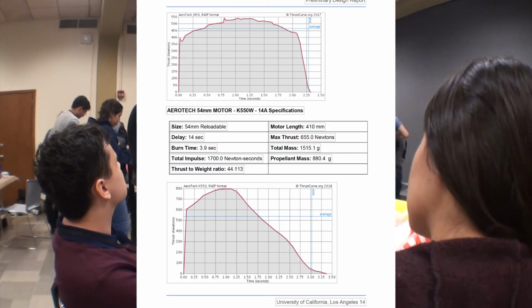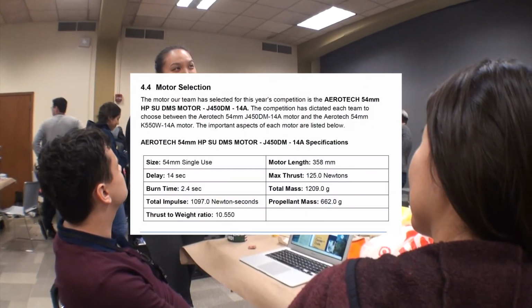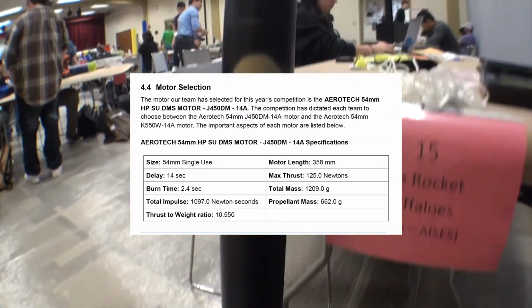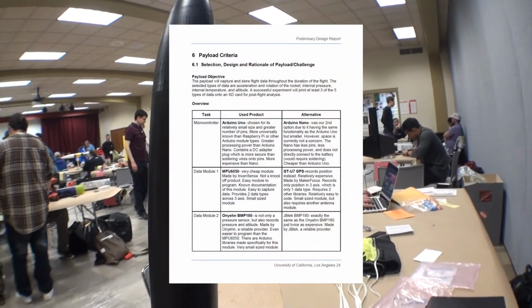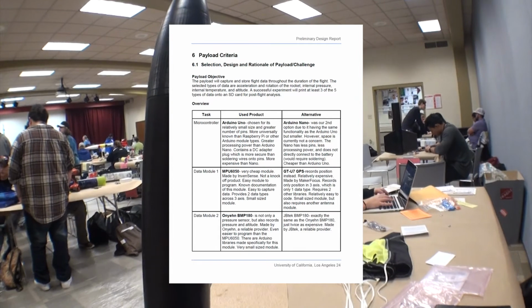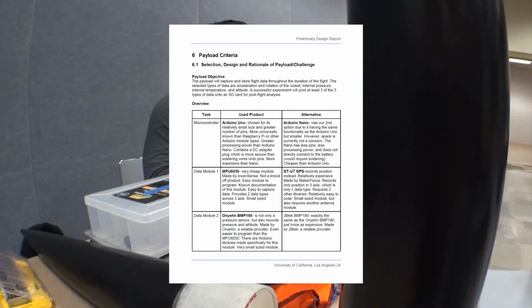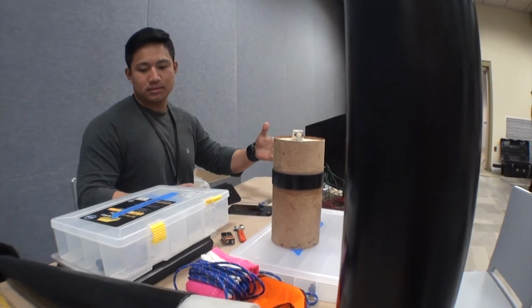Keep in mind there is a deadline for motor selection, after which you can no longer change the motor you will be using for competition. You should also try to determine your payload design early, because payload weight and size are often overlooked in the build process. You can get into trouble if your payload breaks your weight limit.